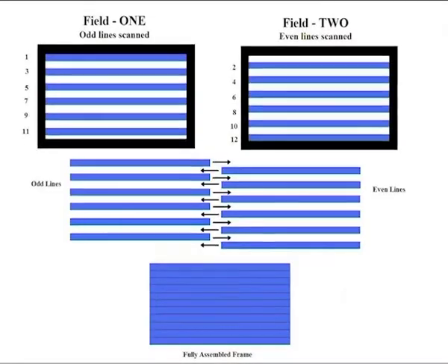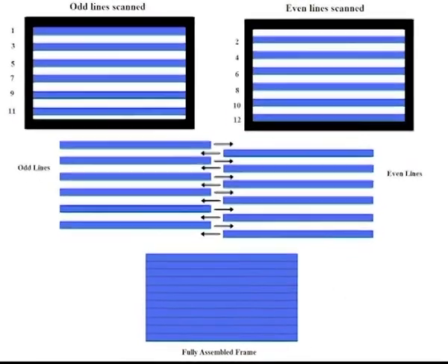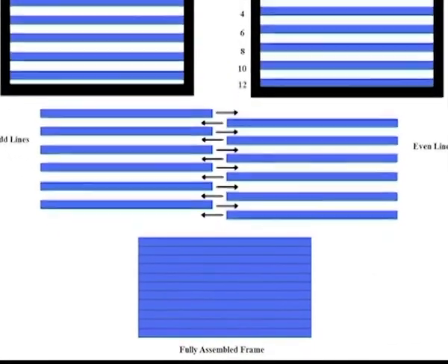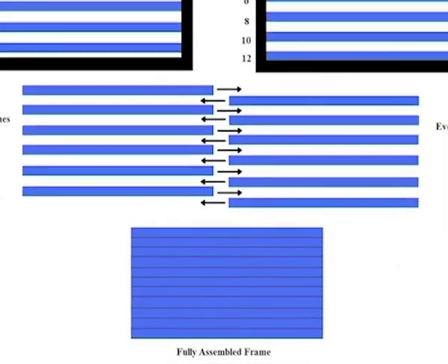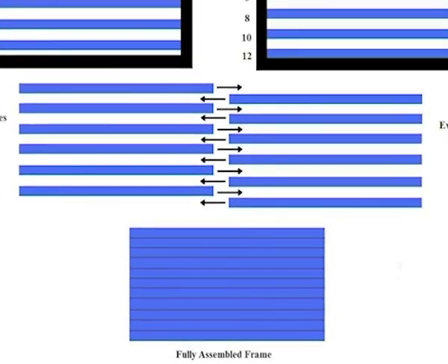In television, the electron beam actually makes two passes on the screen as it draws a single video frame, first laying down all the odd numbered lines, then all the even numbered lines as they are interlaced. On a computer monitor, lines are painted 1 pixel thick and are not interlaced. Single pixel lines displayed on a computer monitor look fine. On a television, these thin lines flicker brightly because they only appear in every other field.